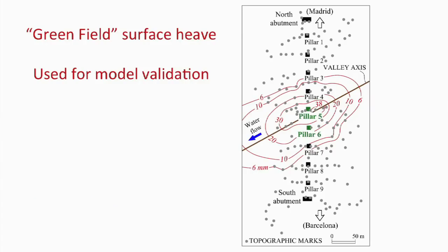But at some particular time, I became involved in this case, and one of the first ideas was to locate marks, just to know a little bit more about this swelling, and what we got in a given time interval was this type of heave. Those are contours of equal heave in millimeters, and you know these are like ellipses, irregular ellipses, and the pillar is here. This is interesting information, and I will tell you why.